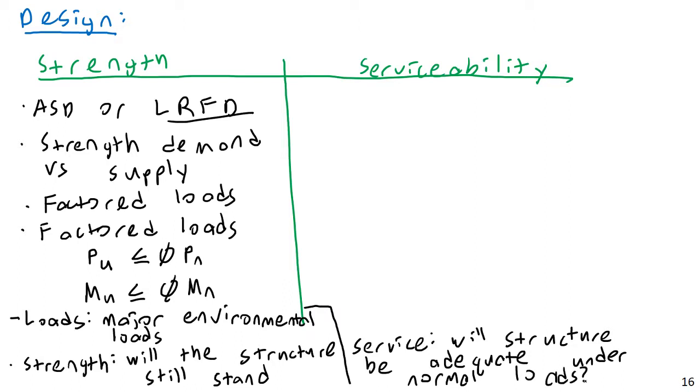Will it be adequate under normal loads? So here we're not using any kind of factored loads. We are using only service loads, and service loads, by definition, are unfactored loads.